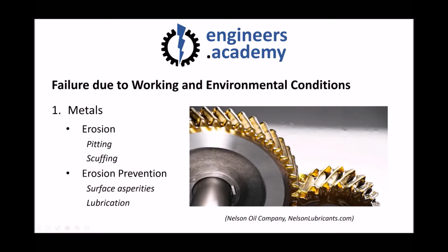So here we see an example of how lubricants can in effect coat the surface and minimise the impact of those asperities. So ensuring that we have the correct lubricant and the correct quantity of lubricant is really important to reducing wear on things such as gear teeth.